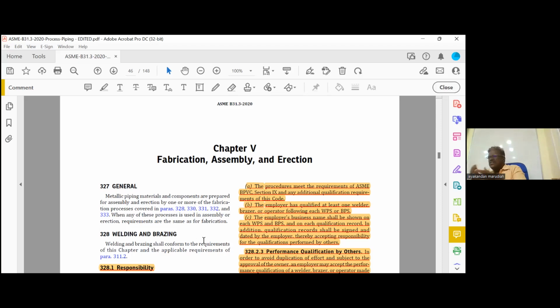There is a condition. Even a common thing: I worked in piping almost 10 years. As per B31.3, lack of fusion and lack of penetration are allowed. But the owner specification will clearly write that lack of penetration and lack of fusion are not allowed in this project. They will not accept it in the radiograph. They have the engineering department, so they will say, this is the code requirement, but we should not accept that one. We have to go more stringent.